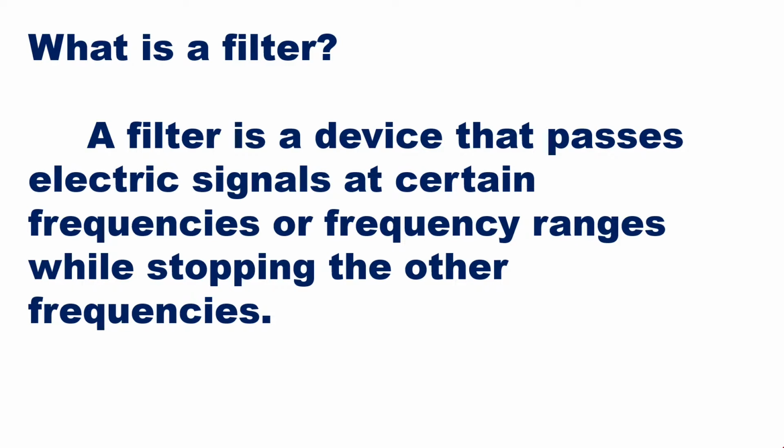Now, in this we have studied types like low pass filter, high pass filter, band pass filter, and band elimination or band reject or band stop filter. We have also seen that a band pass filter we can achieve by connecting a high pass filter and low pass filter in series. Similarly, a band stop filter we can achieve by connecting a low pass filter and high pass filter in parallel and then adding their outputs, amplifying them, to get a band stop filter.